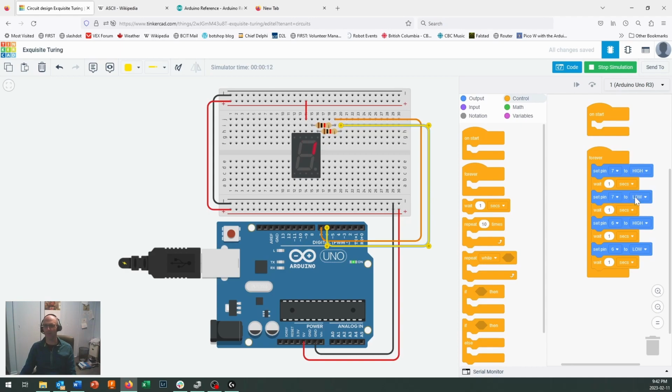Well, you'll recall that what we did here was we finished off by setting it low. Although normally low means something's off, what it means here is that the Arduino pin is in the low state. So when we set this high, it turns the segment off, and when we set it low, it turns it on. Remember, we're dealing with a common anode LED right here.